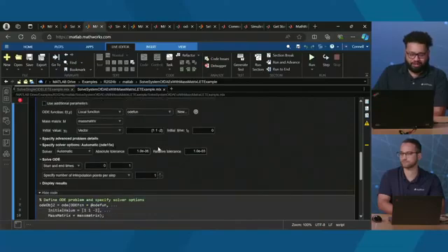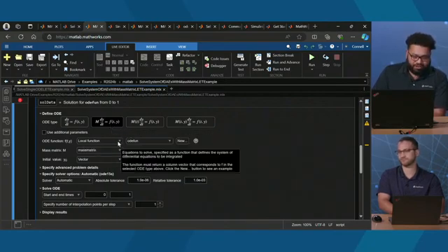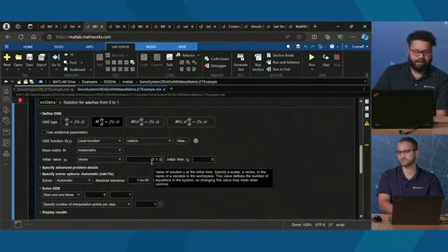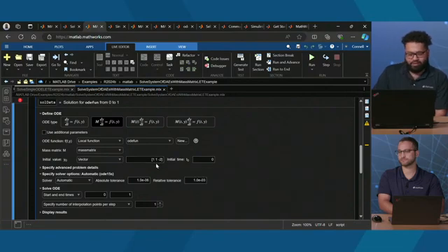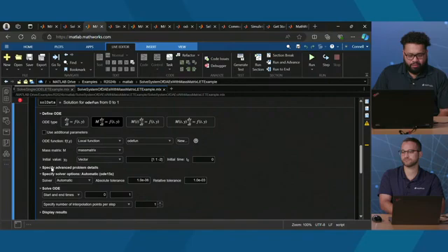So I'm going to show you how this live task works real quick. Essentially, we've picked the ODE type. We've said M dy/dt as a function of time and y. We gave it the local function that we had created up above. We've also got the mass matrix, and we're giving our initial conditions as a vector. You remember we said y1 equals 1, y2 equals 1, and y3 equals minus 2. We're also going to give it an initial time, so we're starting at t equals 0, and we want to run this for 10 seconds. So I say start and end times, not 0 and 1, but 0 and 10.